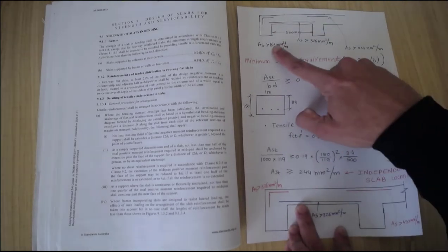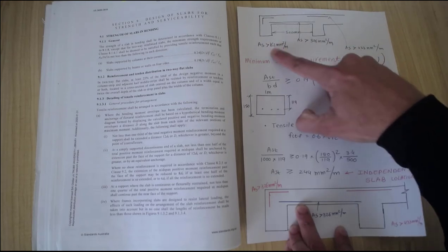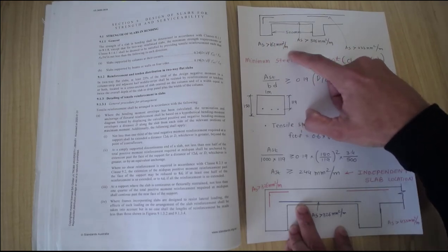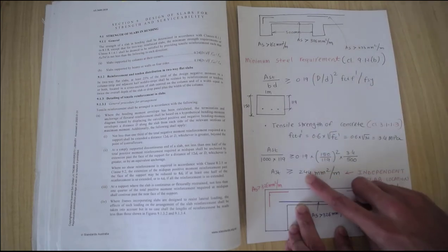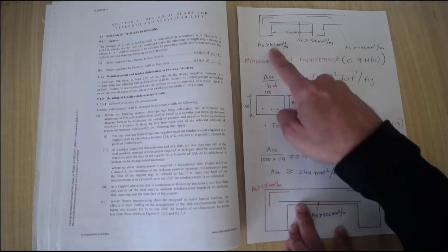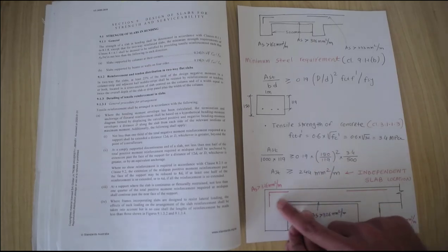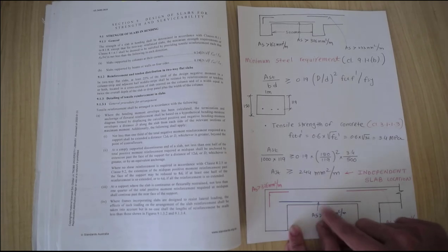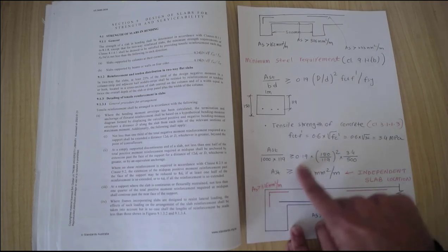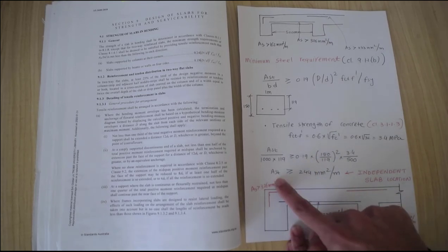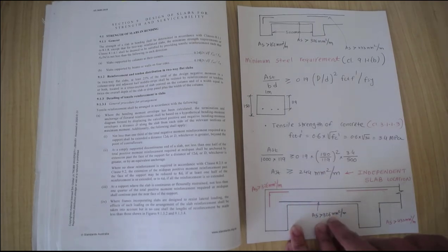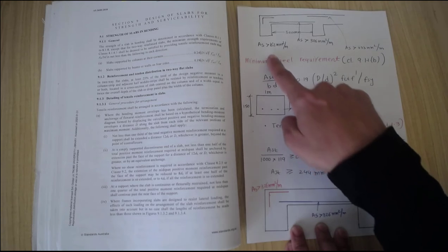But here it is very small, 162 millimeters squared per meter. Now the standard says that you can't use this 162 millimeters squared per meter. You must have at least 244 millimeters squared. So instead of 162, we can use 244, and that would be correct. But then for this different spacing, it is uneconomical, or it costs more to have a different spacing. So let's take the same spacing or same area, that 326 here, 326 here, instead of 244. If you provide more, it is better, and it still satisfies 244. So we just take this value 326 millimeters squared here instead of 162.